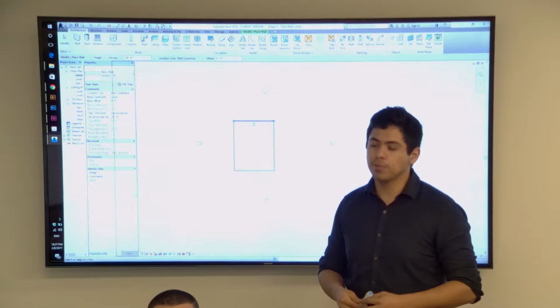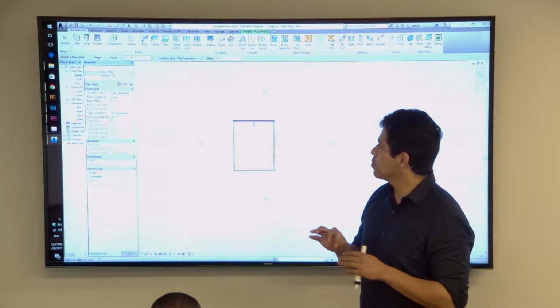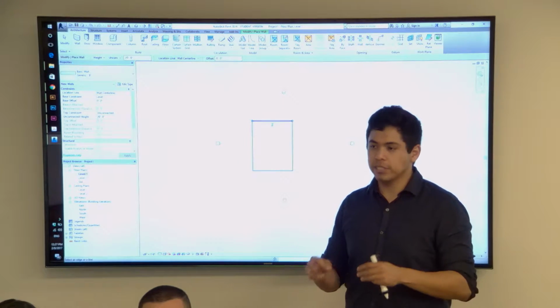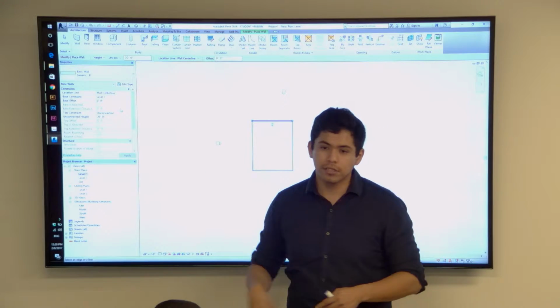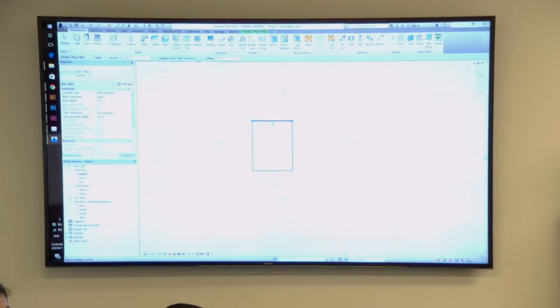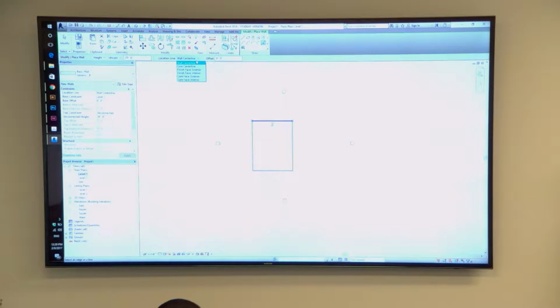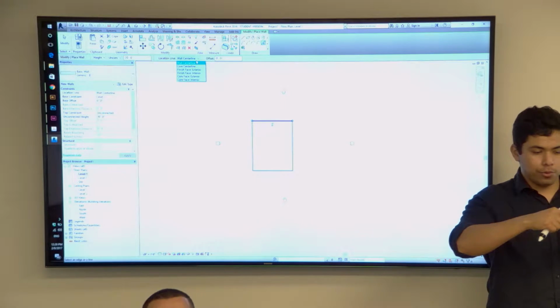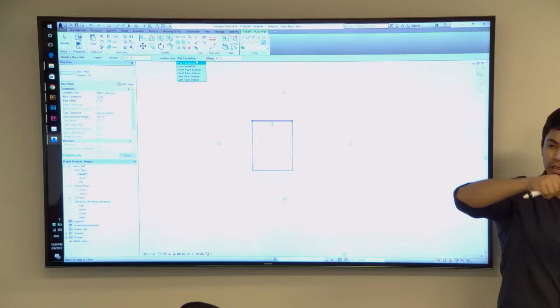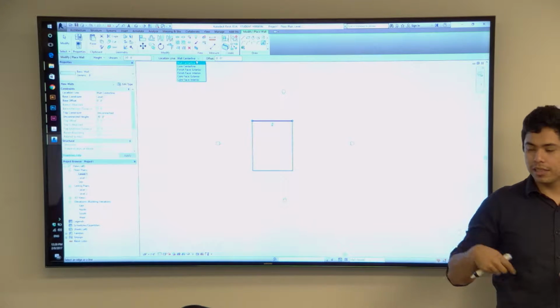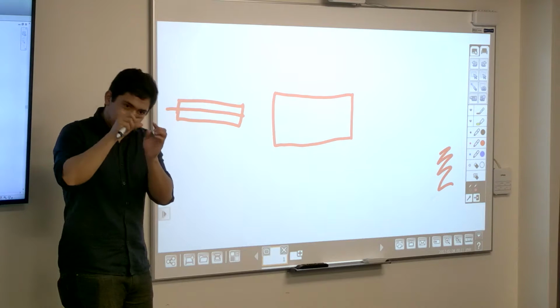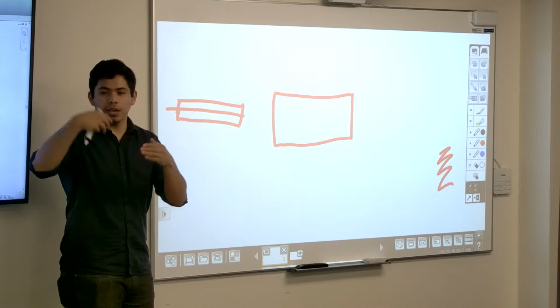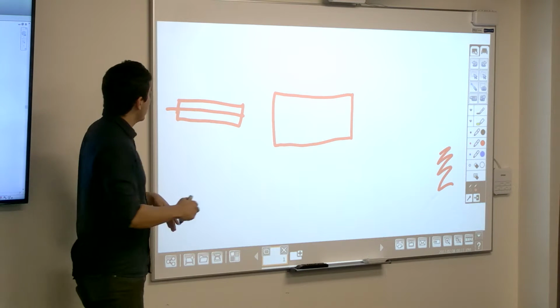And you will run into a problem that most settings are preset to wall line center. That means when you're drawing your wall, it'll draw from the center of the wall. Wall line center, right? This is how, when you have something that's overhanging off of your plate, you know that there's going to be a 4-inch overhang. It'll always center at the half.